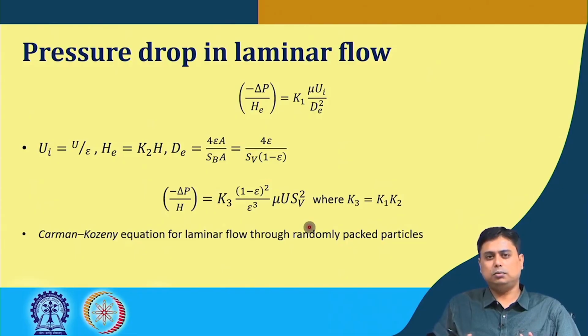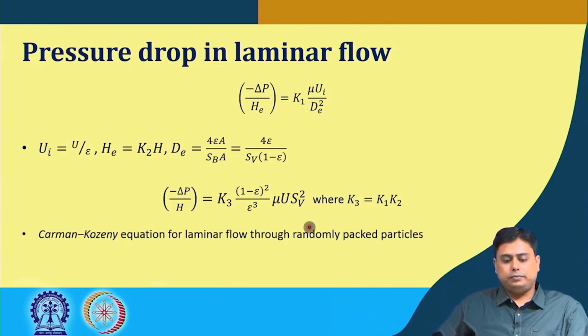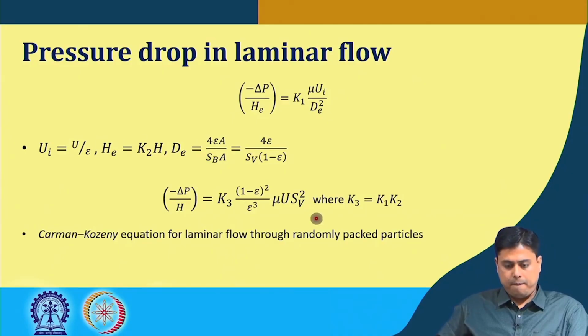Any kind of particle, when there is laminar flow through a stack of those particles, when a fluid is flowing, a single phase flow is happening, the frictional pressure drop across that bed, or the pressure gradient, rather, here it is del P by H that is written here, is given by this expression.